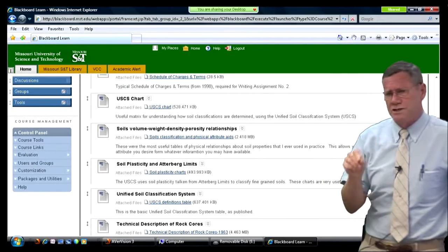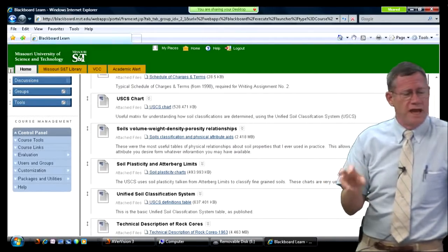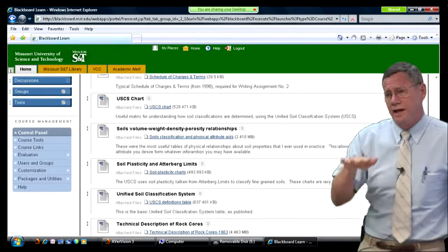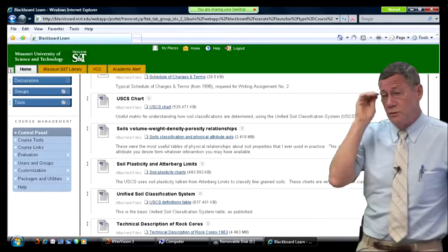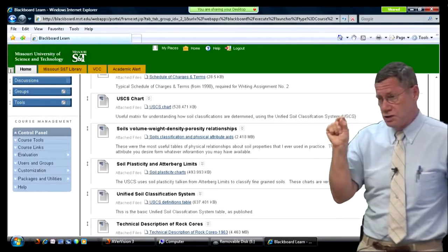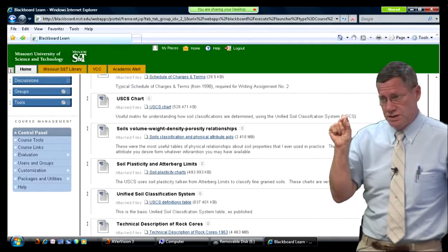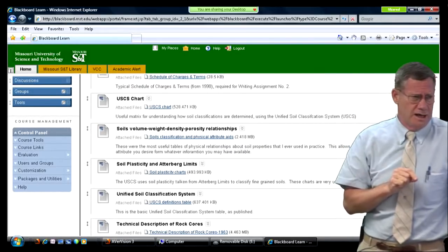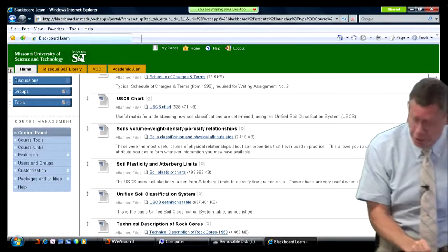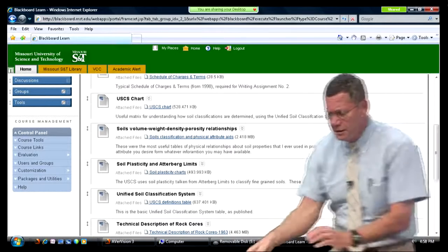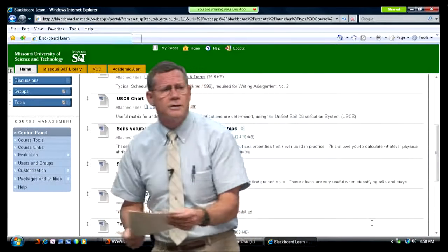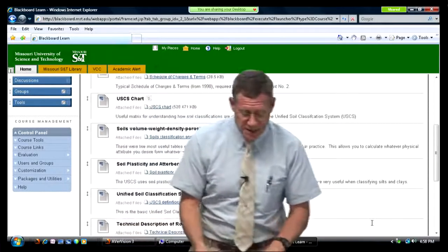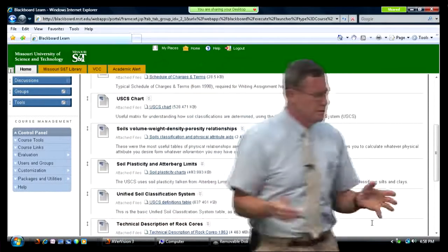That field log is always subject to change based on the laboratory classification tests, which are sieve tests and plasticity indices. And you throw away the field logs. You don't save those, because attorneys will use those to incinerate you on the stand. Because, you know, well, you called this a clay, Dr. Rogers, and over here you're calling it a silt. You know, it's obvious you don't know what it is, do you? It's obvious I'm going to kill you after this courtroom session.